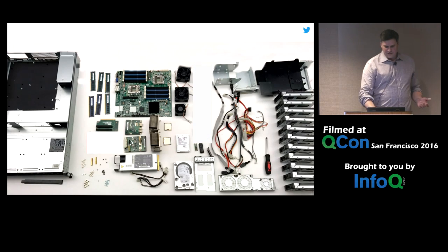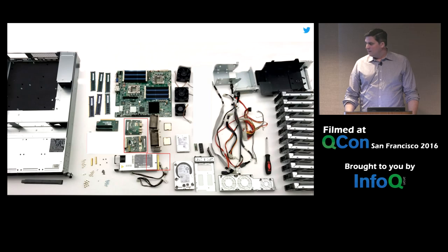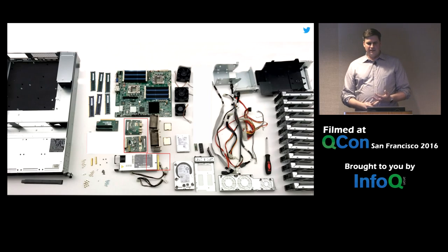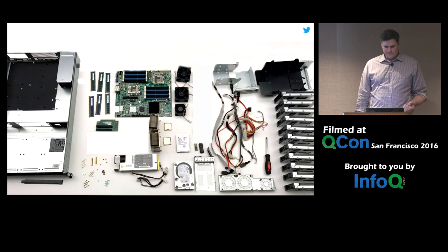Next thing we have in that case is this hot plug power supply. Because it's a hot plug power supply, it needs to mate to a power distribution board, and there's a fan control board integrated as well. Those were two things that ended up failing. The power supply never failed, but one of the little boards it was attached to would fail. So we really want to get rid of those two.